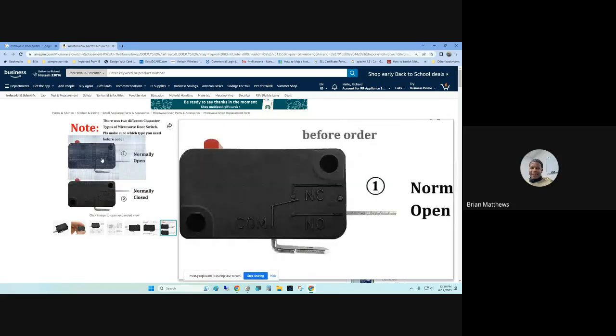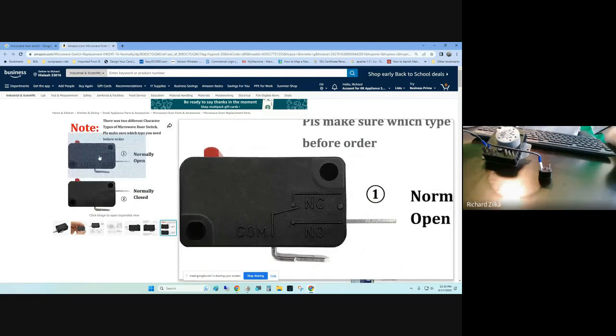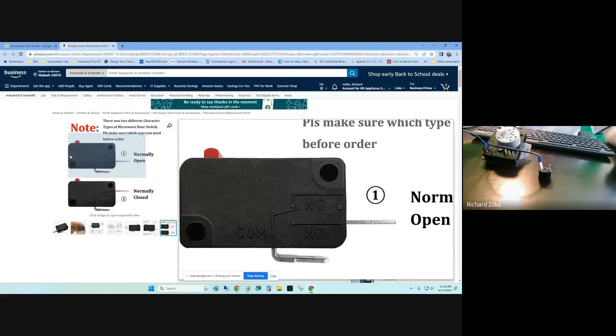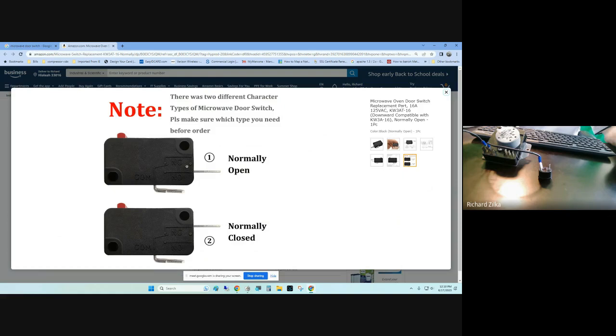Normally closed. Okay, you sure it's normally closed? Look at the pin location, and I can't keep it open. There we go. This one has a normally closed here, and the drawing is showing common to normally closed, but there's no place to connect a wire up here. Okay, if you look at the bottom one, it says NO, and you have a place to connect a wire. So you can only connect a wire on the bottom here where it says common, or you can connect the